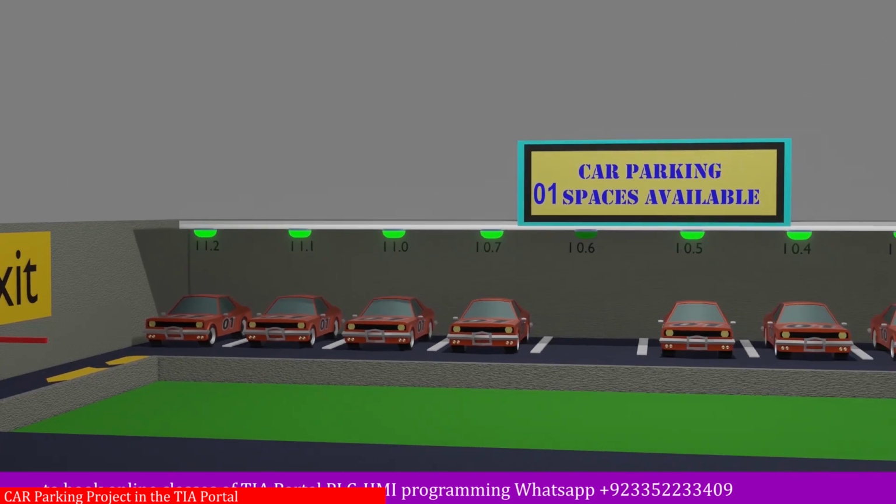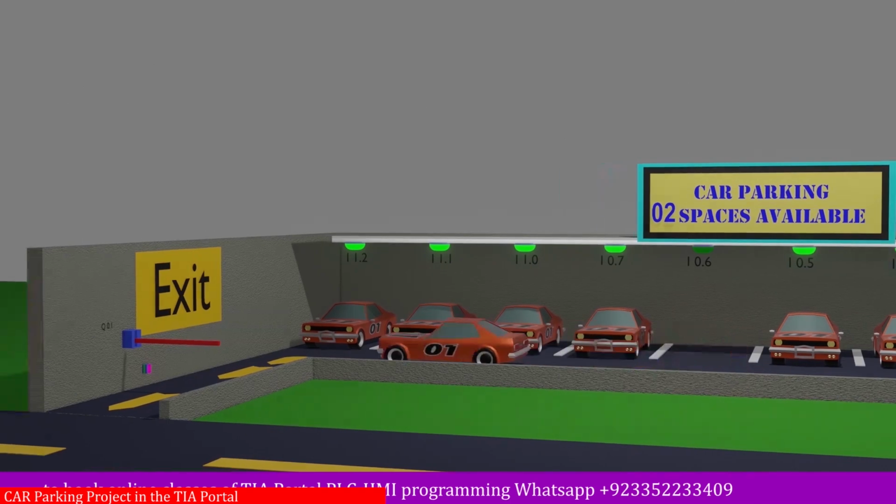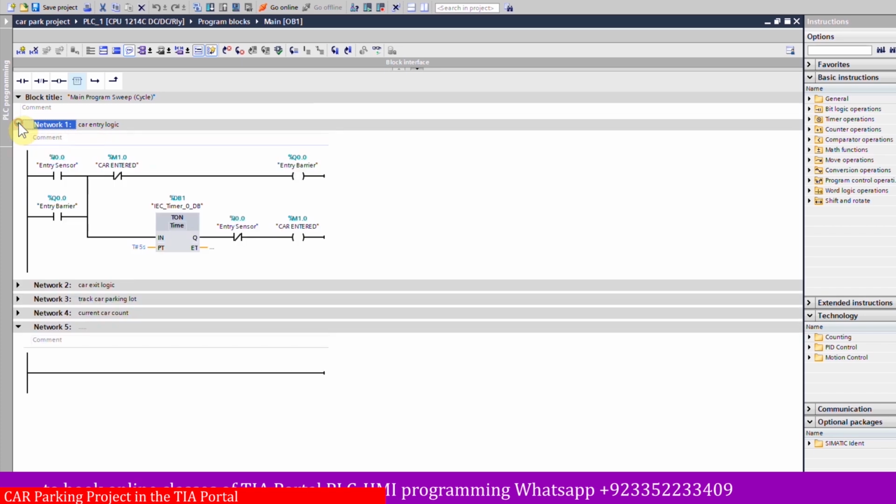Now let's go to the TIA Portal software and see how we can make the ladder logic for today's project. In network number 1, we have a logic for the car entry. Whenever the car comes in front of the sensor I1.3, it will hold on the output Q0.0 through its own normal open contact. In parallel, it will start the 5-second timer.